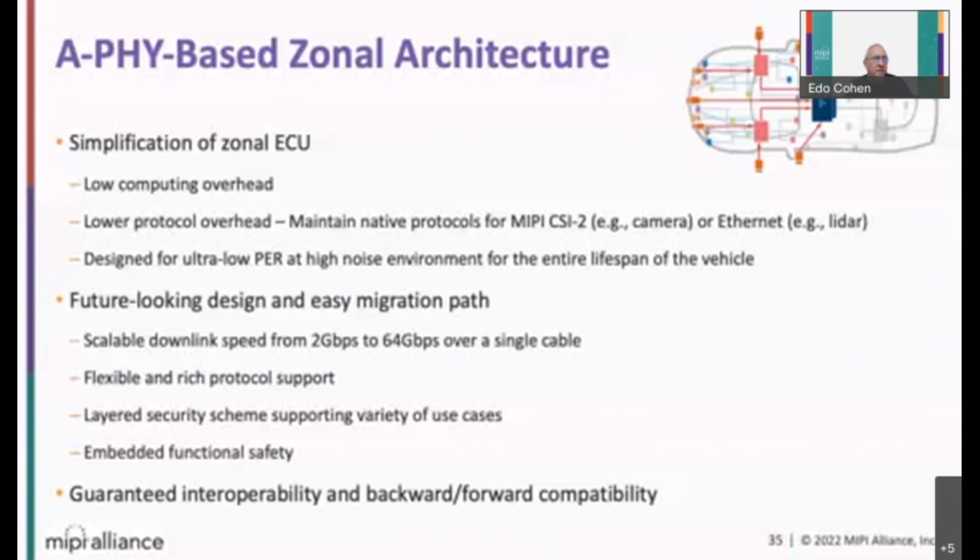So just to summarize the A-PHY-based zonal architecture. In cases where the main components are going unidirectionally to the main CPU unit, as cameras and radars, A-PHY provides simplification of the zonal ECU. It has low computing overhead due to the hardware-based solution. It has lower protocol overhead as it maintains the native protocols like MIPI CSI-2. And it's designed for ultra low packet error rate in a high noise environment, so for the entire lifespan of the vehicle.